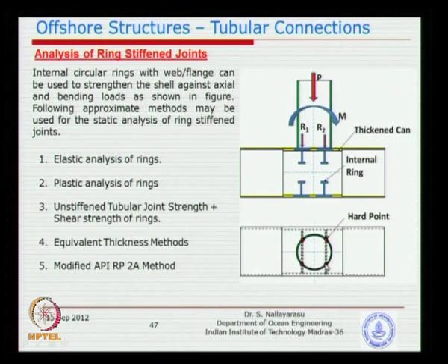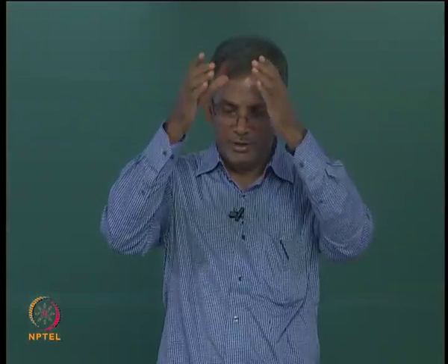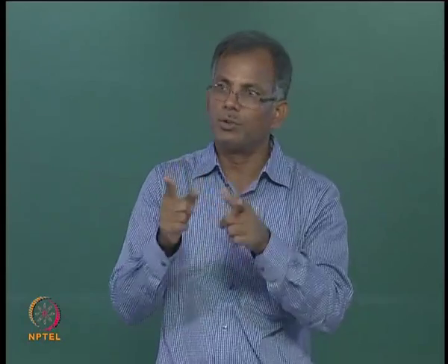What about the loads elsewhere? You could decide to divide the total load P by 4, and each point carries 1/4 of the load. But this is true only if it is a vertical brace with only 2 stiffeners, and only for axial load.